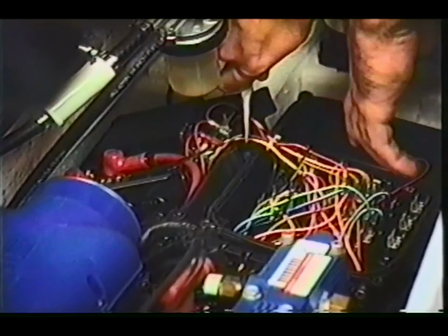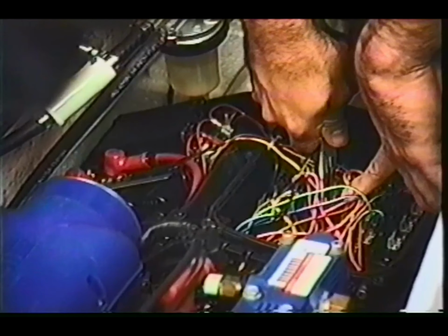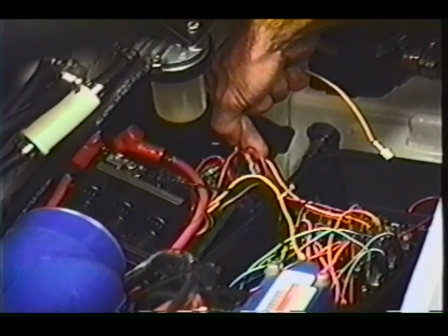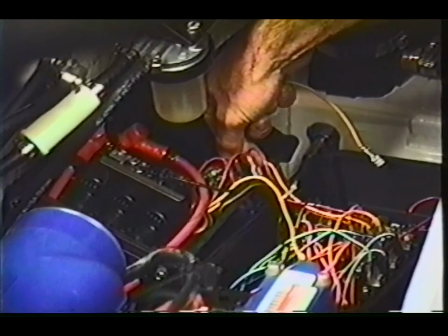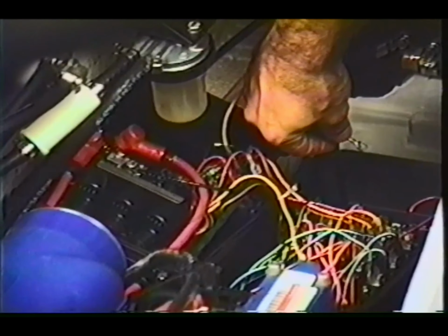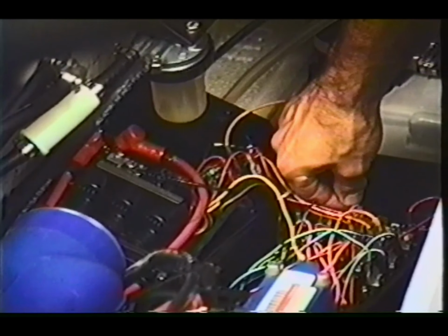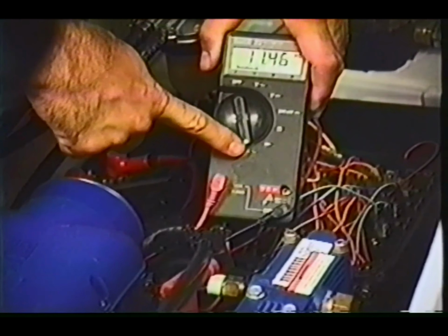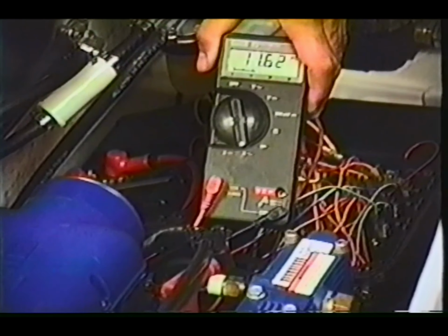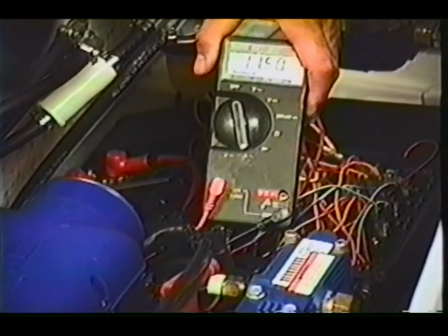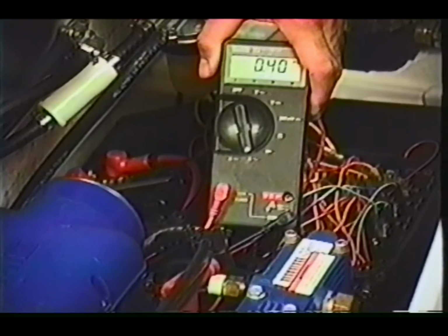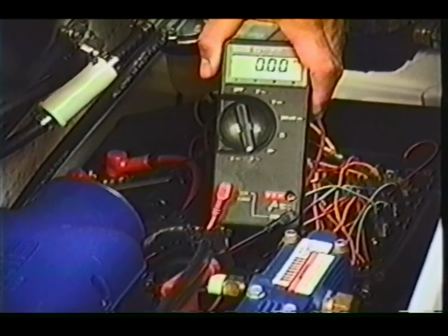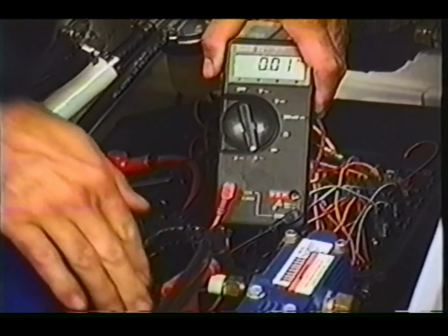To test the personal watercraft alternators, disconnect the red with purple and yellow wires in the electrical box and connect a jumper wire between the circuit breaker and a positive battery voltage supply. This provides power for the starter button. For the AC amp test, always make sure the red meter lead is in the 10 amp outlet and the selector dial is switched to the AC amp position. Connect the meter leads to the red with purple and yellow wires coming from the stator and quickly test with the engine running at idle.